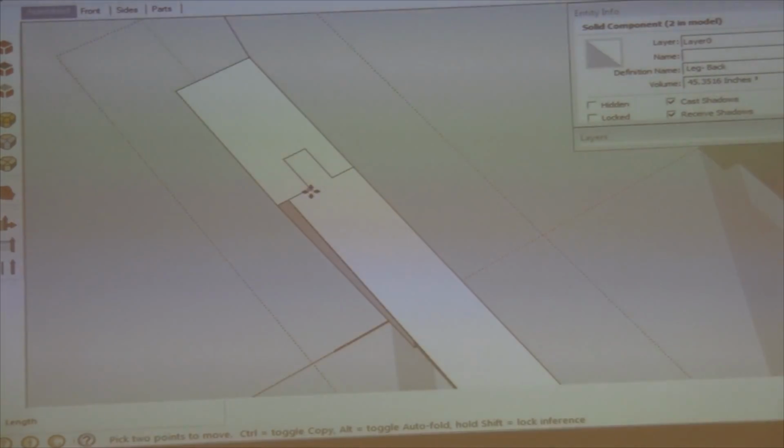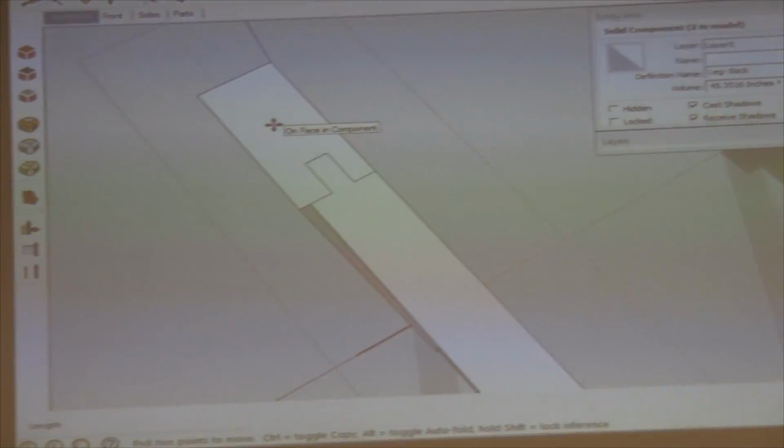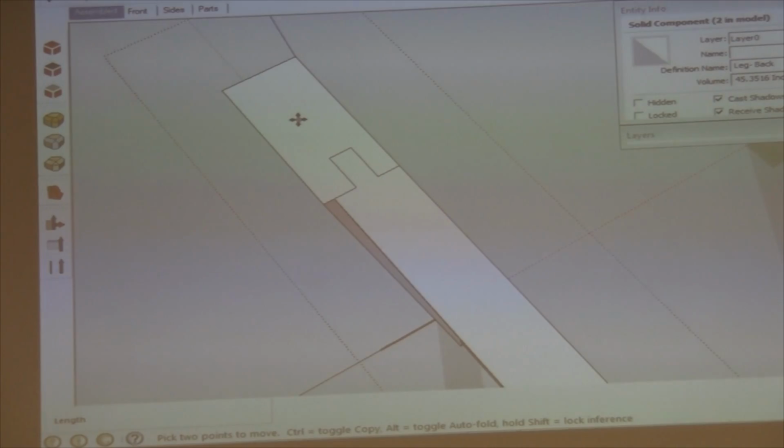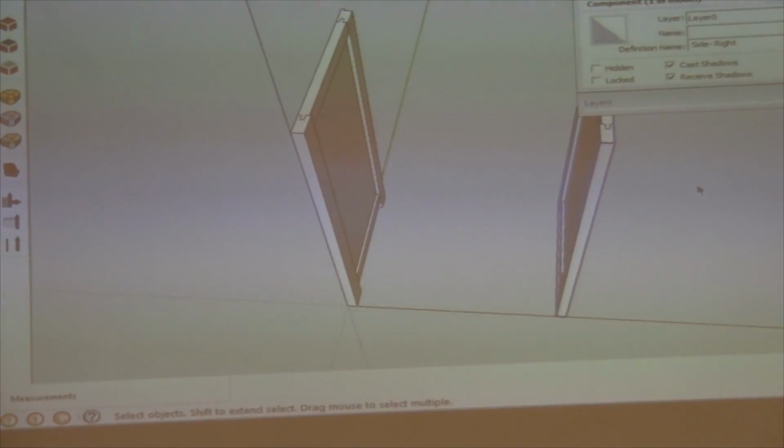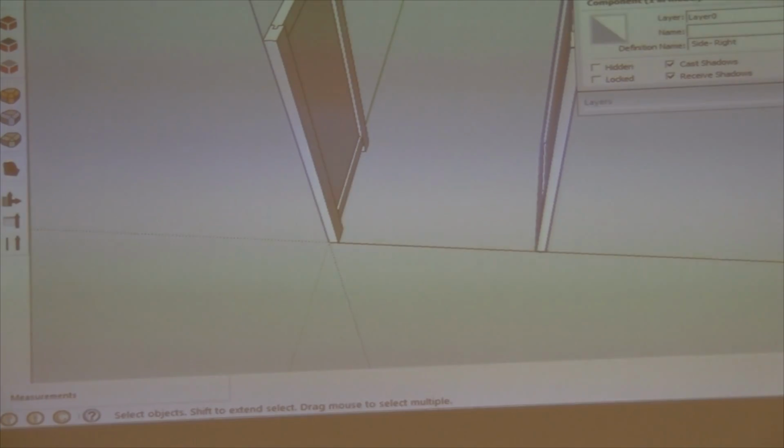Yeah. And that is another thing. We could have made this a little bit simpler by making the rails 7/8 of an inch thick wood as well, same as the legs. So it would have simplified it. But I'm also cheap on wood, and I've got plenty of 3/4 inch wood, so I don't want to end up using 7/8 inch wood where I don't need it. So that's why we made a design choice there. It's all choices. You can do it any number of ways. So now we have these two components lined up properly, and we just double check my measurement.